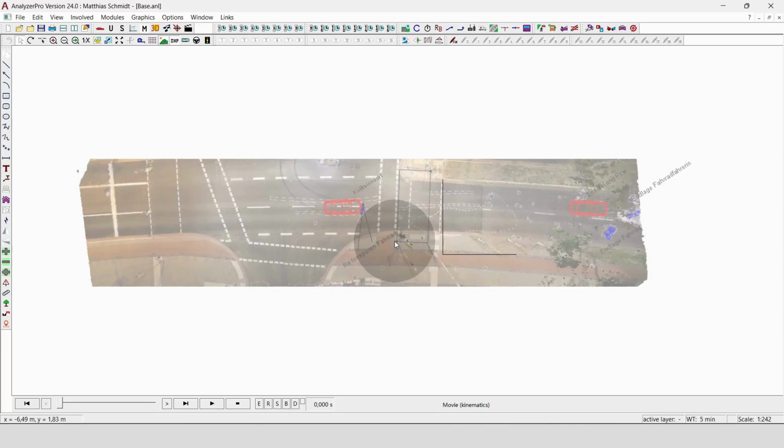Today we're going to talk about the topic of pedestrian and cyclist accidents, specifically with a special method to deal with these cases, which is called the barrier method. All you need for that method is a final position of the car and the pedestrian or the cyclist. It's not so important to have the final position of the bicycle, but the cyclist itself and the car is important. We do not need a precise collision position. That's something we will find out in the process.